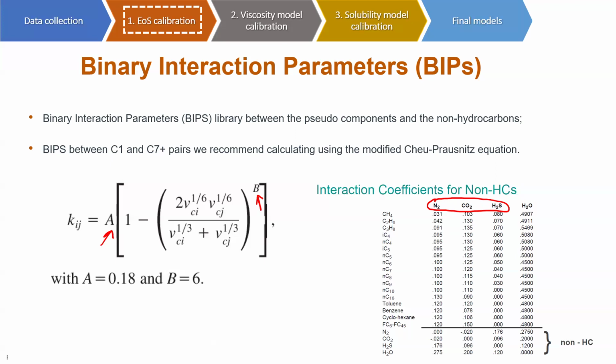And also, if there is any impact of phase switch, because if I have one component missing in my reservoir fluid, for example, I have a conventional compositional analysis of an oil reservoir, and it doesn't have CO2 for now, and then I'm doing a swelling test or slim tube test, and putting CO2. So I need to have a parent compositional model and then need to include CO2 with the next experiment.